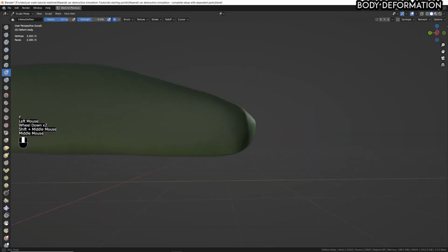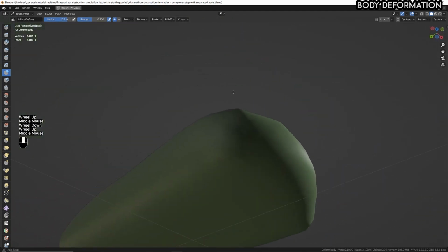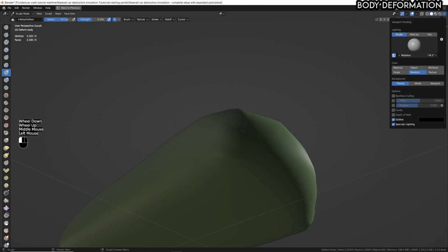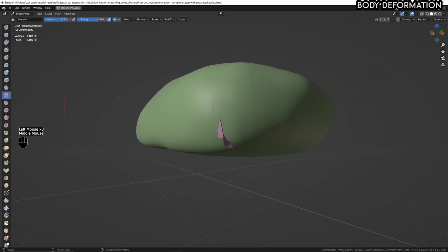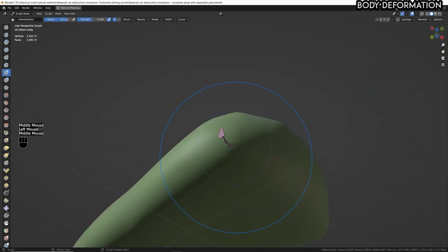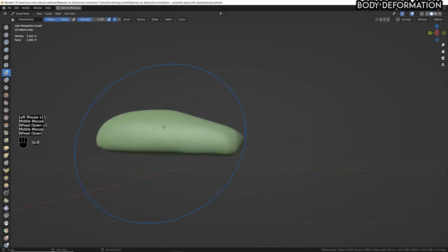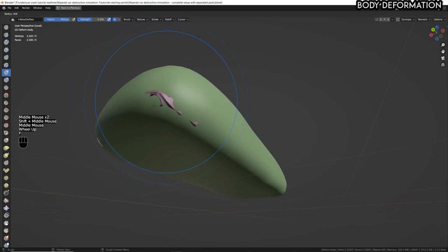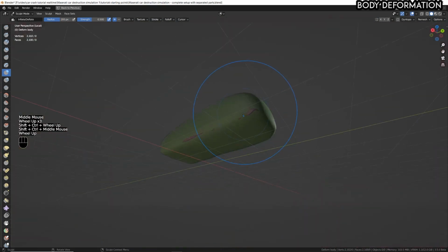Let's go on this way, and just ensure that you are not creating this type of ugly corners. As I said before, they are going to generate some self-intersection, so I'm going to adjust this by smoothing. There is the smooth tool here that is useful for this purpose, and by the way, we have to inflate it more after the smooth with a very big brush like this. All right, this is smoother. I'm going to inflate also this part here, with just some gentle touches until they are covered. All right, and just go on covering all the little parts that need it.